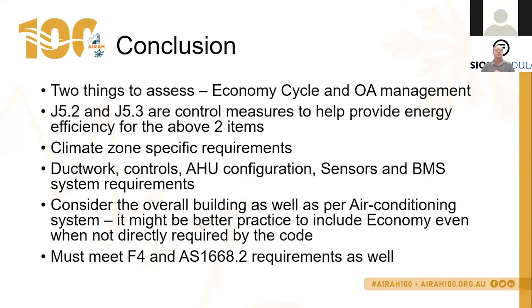Yes, it would. You do need to commission and locate your CO2 sensors appropriately to ensure that they do operate correctly. So part of your commissioning process and your location, your CO2 sensors, is in ensuring that they do operate and read correctly, and there is calibration required.